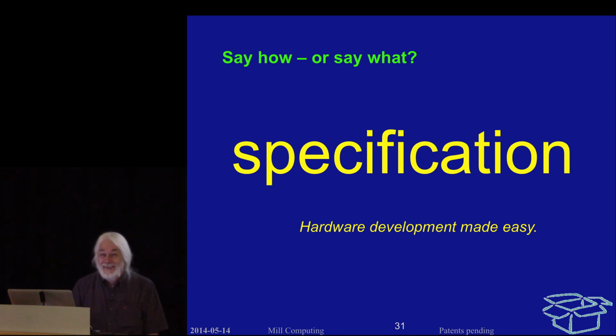And part of the tools is also, you mentioned HWJet, which I assume outputs like Verilog or something. What winds up being produced for the hardware guys is a set of C++ Verilog drivers that are themselves compiled, and when that program runs, it spits out source Verilog. This tool doesn't produce Verilog. That requires too much Verilog knowledge, and we don't want to put it all in. Instead, this produces drivers that go through yet another tool chain that ultimately produce Verilog. And then there's manual steps after that, as I said. The software side is all mechanically done, but the hardware side does require manual steps.